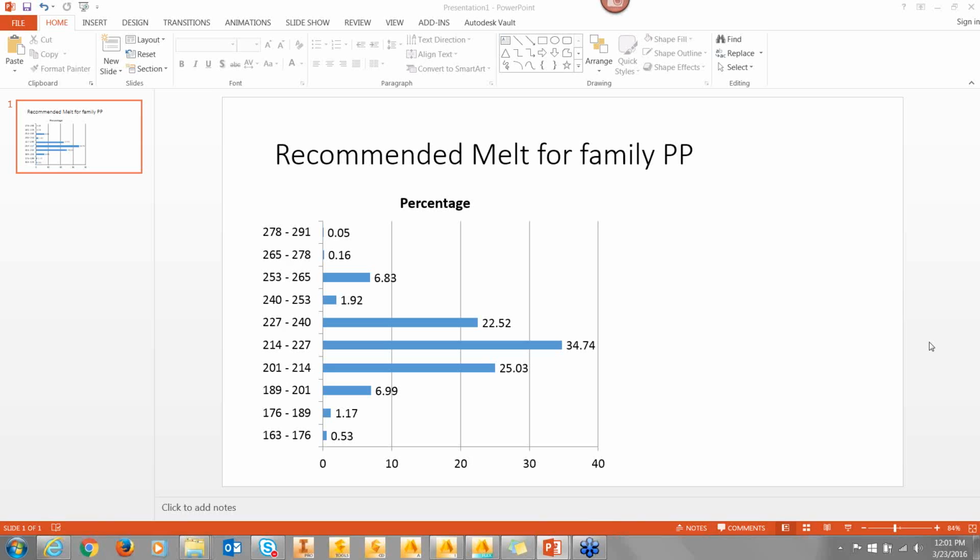Guide me to use Excel VBA for multiple instances of Synergy. That's something that we would probably have to talk about offline. You can use Excel to drive things inside of Synergy. For instance, if you had a bunch of analyses that you wanted to run with different melt temperatures, different processing conditions, even different materials, you could set up an Excel spreadsheet and then call a script from the cells to open Synergy and run those for you.